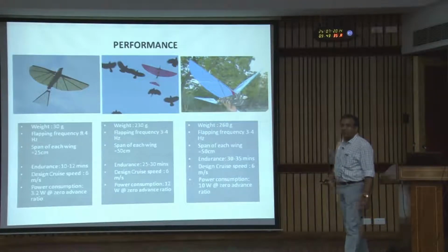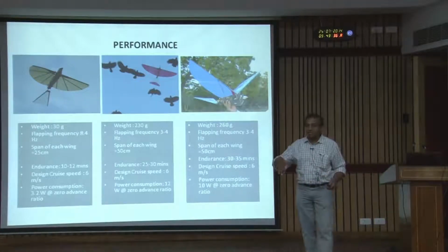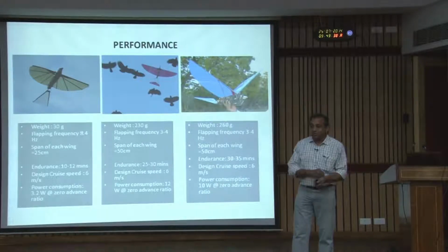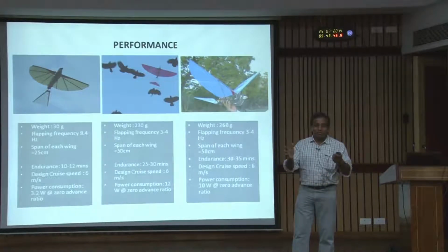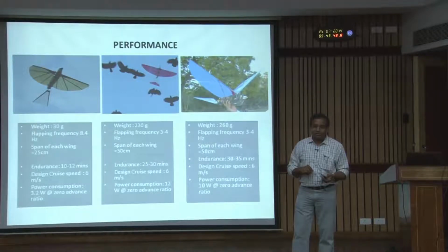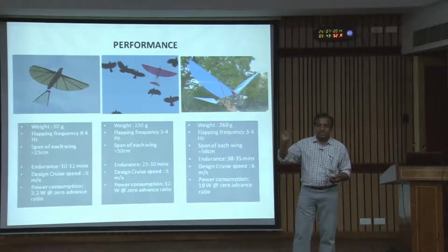These two stiffeners need to be flexible and they need to be lightweight also. So balsa was not doing the best job. So what we did, balsa wood, you will be familiar with if you do aero modeling. What we did is we took the bamboo skins.